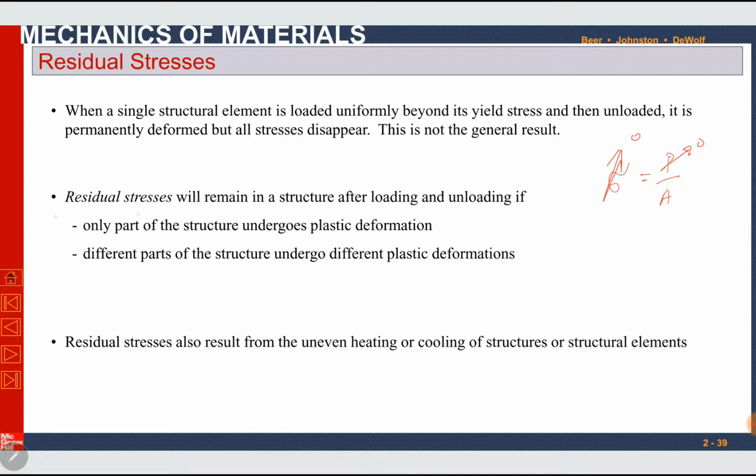Residual stresses will remain in the structure after loading and unloading if only part of the structure undergoes plastic deformation. So after plastic deformation, you cannot make stress equal to zero. Different parts of the structure undergo different plastic deformations. So it doesn't mean that the whole structure will have the same amount of deformation and the same amount of stresses.